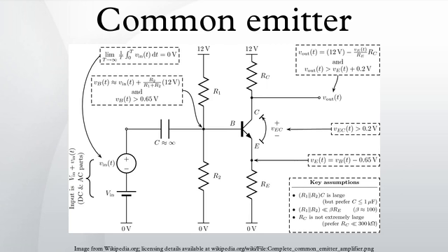Characteristics: at low frequencies and using a simplified hybrid pi model, the following small signal characteristics can be derived. If the emitter degeneration resistor is not present, then the expressions effectively simplify to the ones given by the rightmost column. As expected, when the resistance is increased, the input impedance is increased and the voltage gain is reduced.